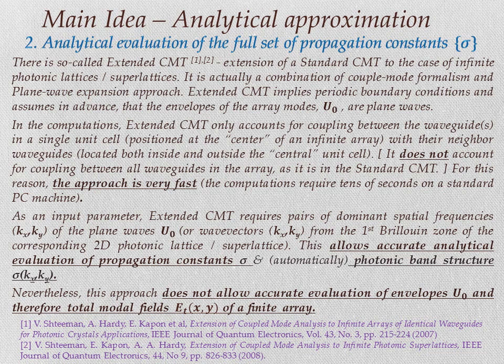It does not account for coupling between all waveguides in the array, as it is in the standard coupled mode theory. For this reason, the approach is very fast. The computations require 10 seconds on a standard PC machine.